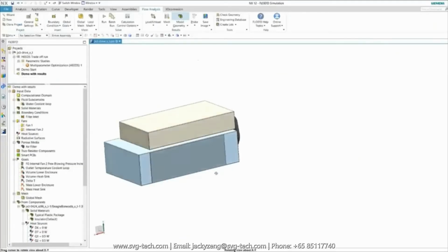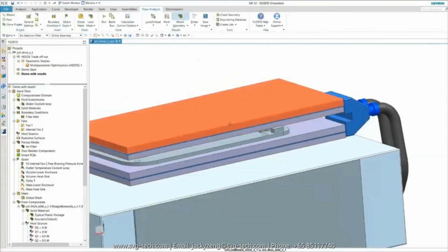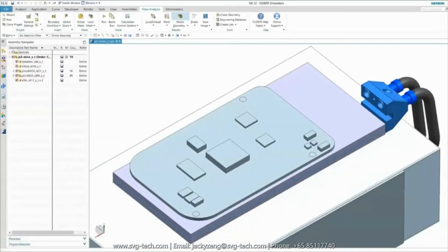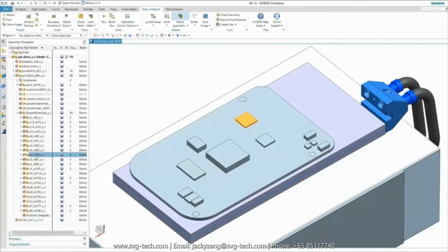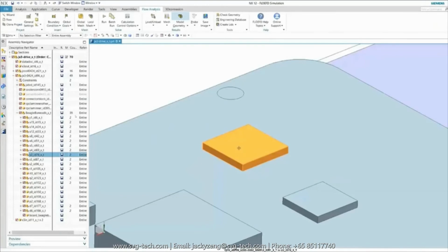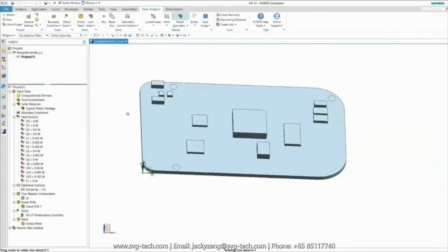So let me show you where this geometry sits. So hiding the enclosure, hiding the cold plates, and then I'm going to zoom into the model and show you where this geometry lies. So it lies over here. So that is the component we are going to replace using a component from the package creator. This is also touching on another very useful functionality in FlowEFD.